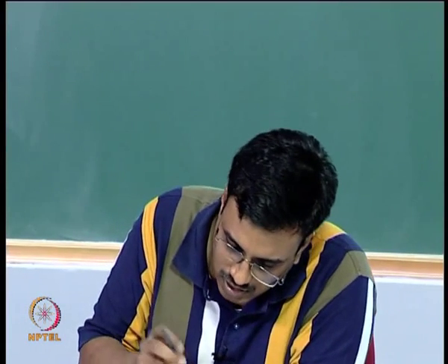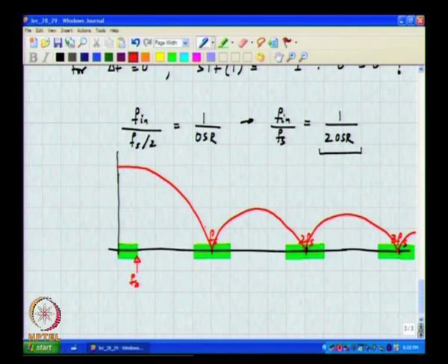And what I am saying is that in the special case of the first order system we have been discussing, this alias rejection, which is the maximum gain in this band, the attenuation of these signals will be at least 1 by OSR times 2. Is this clear?